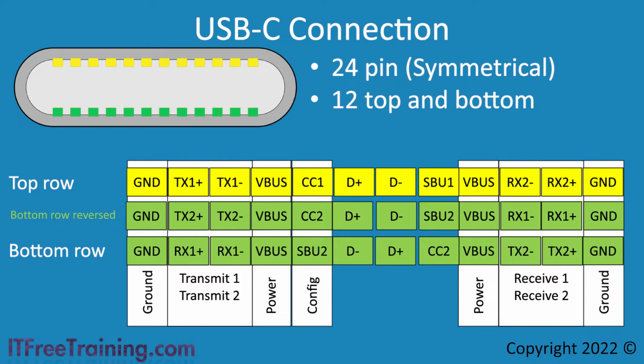USB-C has the ability to change the signal and control which wires are used to transmit what signals. More on that later in the video, but the important point to take away here is that the configuration channel is used to determine what wires in the cable will do what and what protocols will be used. For the moment, I won't worry about what we can do. I will worry about what happens in the default case.